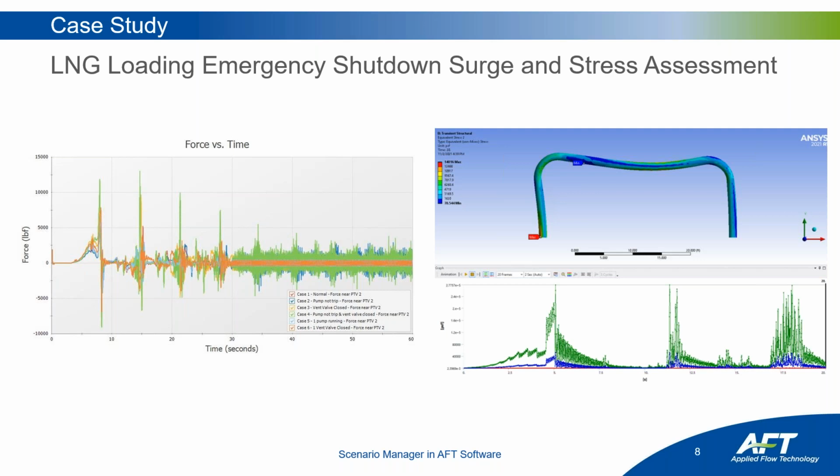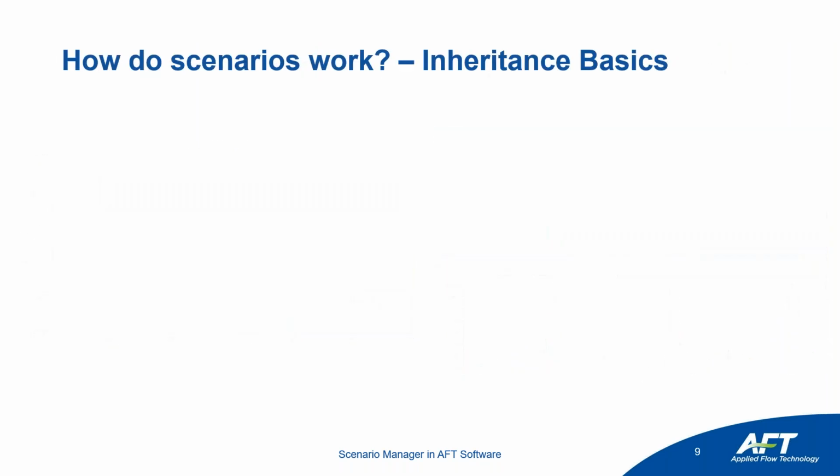So here they use scenarios again to evaluate combination of different failures and then also sensitivity. What if we change the valve characteristics of the closing valves? How would that impact our surge response? So those are some case studies that again reinforce applications for scenarios.